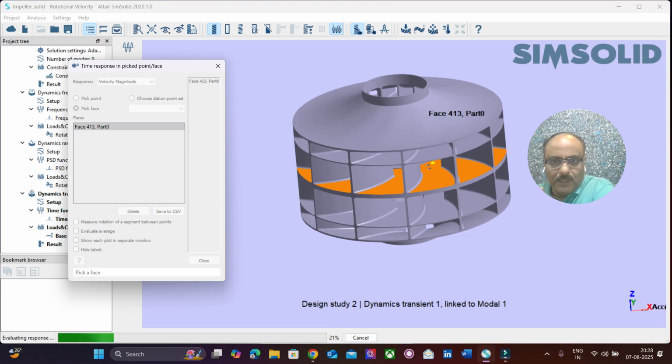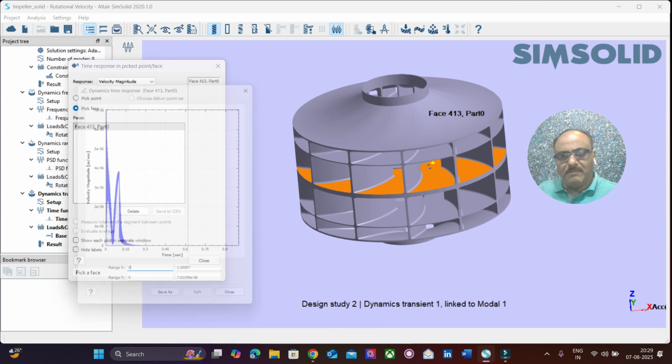Okay, so this is how we will find that acceleration, the g force whatever we have given to the structure, with a rotational velocity of about 800 rpm. How is this going to excite the structure? It is nothing but a modal superposition. You already have a rotational velocity, and you also have a base excitation. So there is a mode generated from the rotational velocity, and there is a mode generated from the external excitation or base excitation.